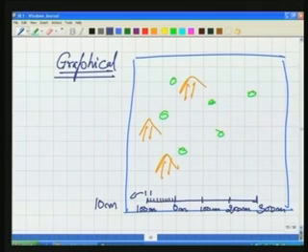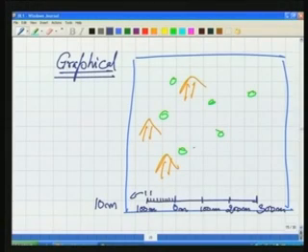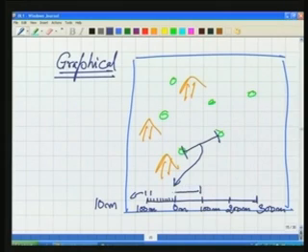Now, what is the meaning of this? What are we doing? We are writing a scale on our map. Now, for any distance between two points, if I can measure this distance, I can bring this distance here and keep it against the scale. So, you can measure the distance to be 100 meter plus 1, 2, 3, 4, 5, so 150 meter.